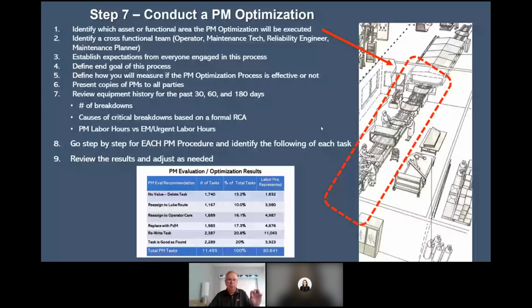So down below, we got the PM recommendations. When you look down at the steps on that PM, it says check chain drive. Well, maybe we're doing something else to check the chain drive. So let's just say there's no value added, especially if you do PDM on it.